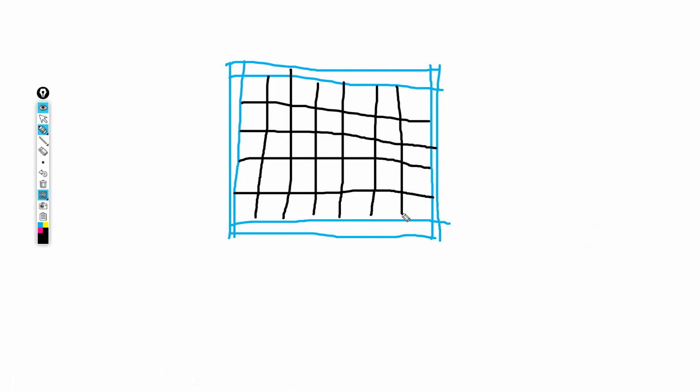Now, what we are doing right now is called finite element analysis. In finite element analysis, we are interested in decomposing the loads from this slab, and then they are transferred onto the nearby perimeter beams. But then that load is going to be transferred through these points which are attached to the beam. Finite element analysis is about discretization of the entire slab panel into small target element sizes.